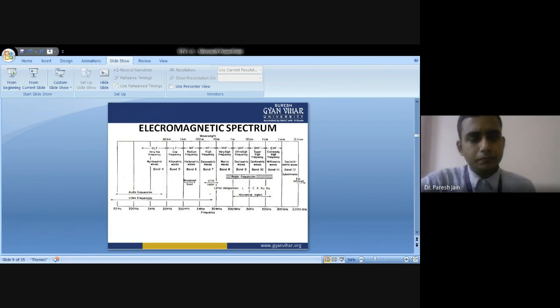For example, although the nominal frequency range for L band is 1000 to 2000 megahertz, an L band radar is thought of as being confined within the region from 1215 to 1400 megahertz, since that is the extent of the assigned band.